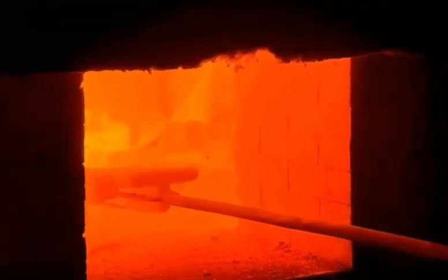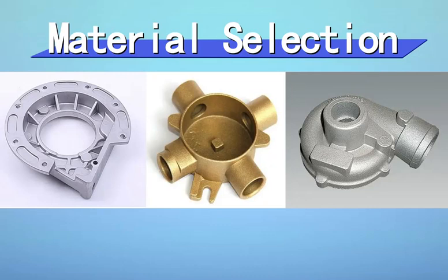Material selection. Investment casting offers a wider range of material options as both ferrous and non-ferrous alloys can be used. On the other hand, die casting is mainly adapted for materials such as aluminum, zinc, and magnesium alloys.